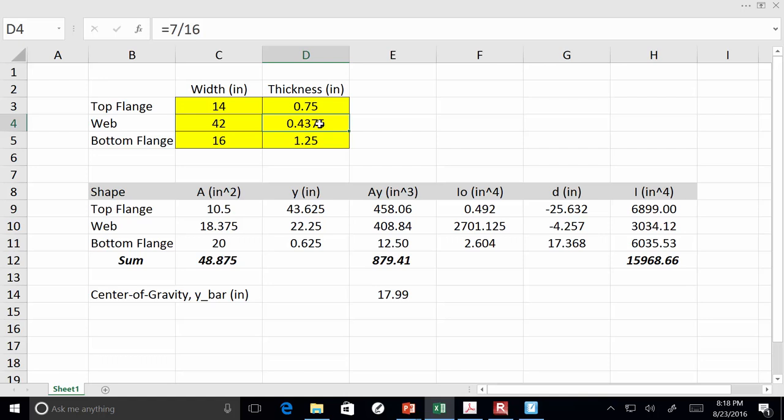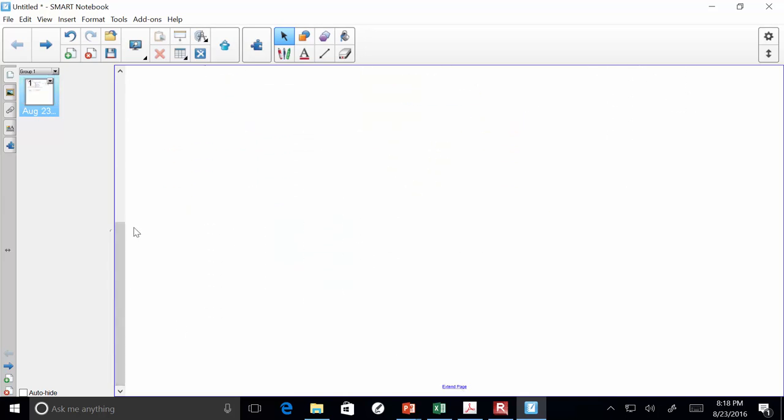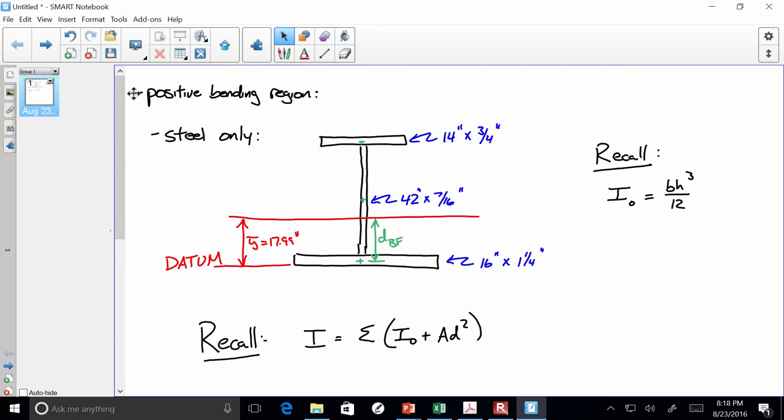Let's look at a composite section. Okay, let's do a composite section. So technically, if we're looking at this bridge, we've got 4 sections that we need to consider. Okay, 4 composite sections, because we've got short-term composite sections, we've got long-term composite sections, but we also have interior girders and exterior girders, right? So let's see if we can keep this simple. All right, let's just do one of them because they're all going to be the same except for the width.